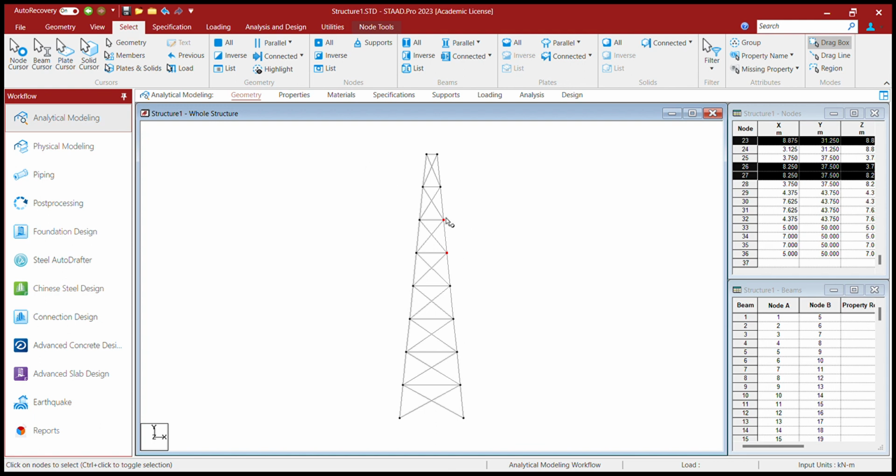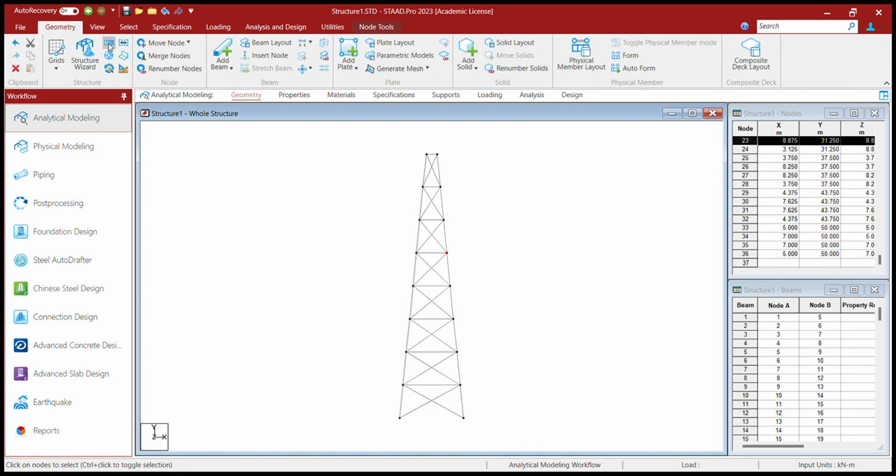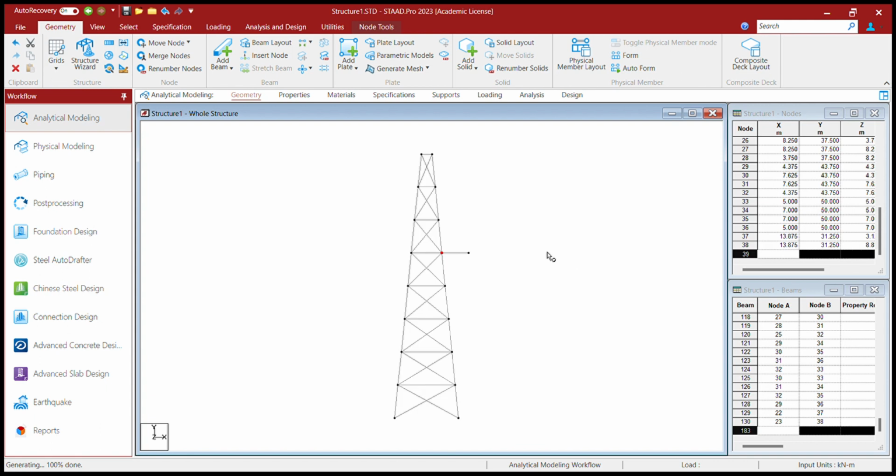Oh sorry, we don't want this point right now. We'll just deselect it, and we want a cross arm of 5 meter at this point. So only for those points we'll make a translation repeat for 5 meter in x direction with a linking of step. Okay, so the point is there. Now we'll create